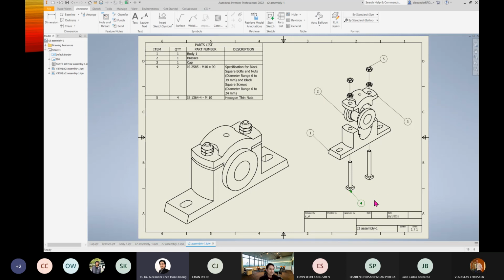Okay, try that. So now, if you get this, you can see that your assembly drawing over here is complete. For an industrial assembly engineering drawing, you have the exploded wheel, you label them properly, you have a part list, and you also have an assembled wheel over there. For an assembly drawing, this one is good, for basic. So I save it first.